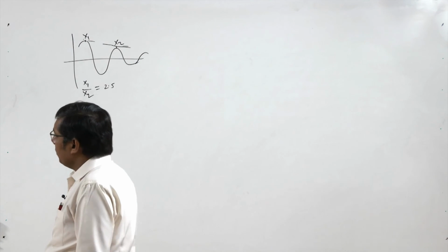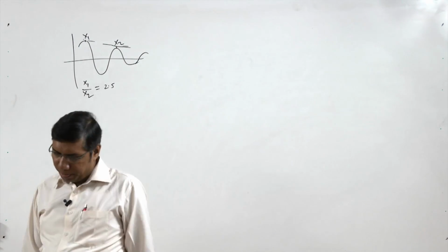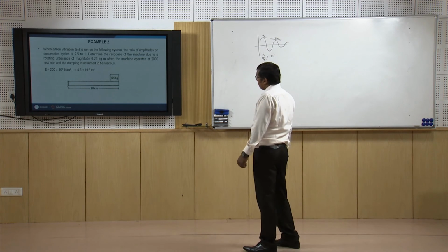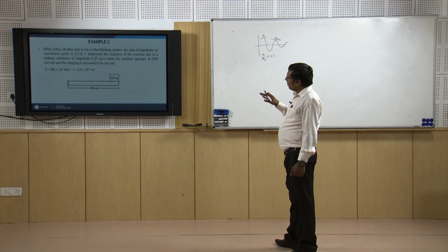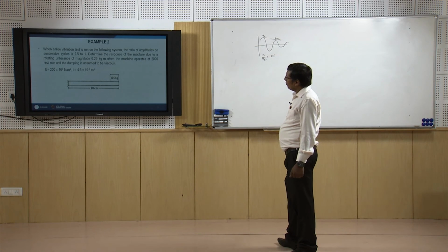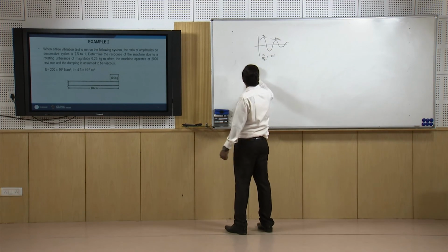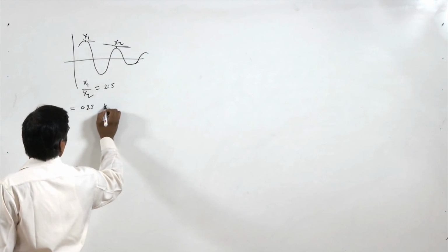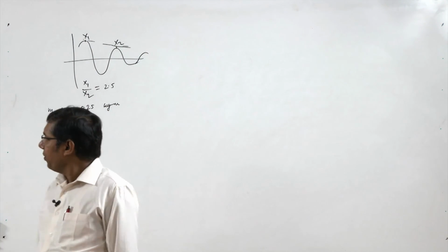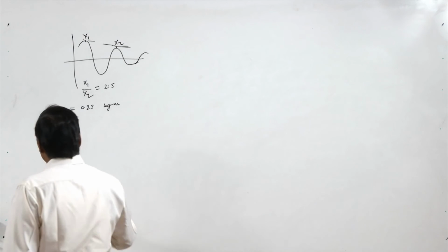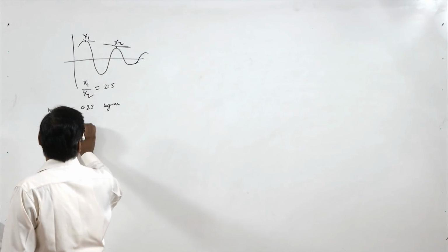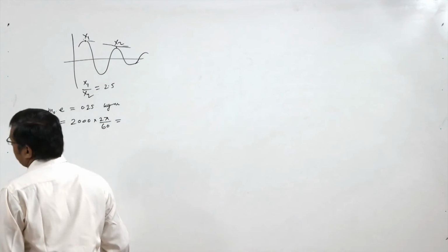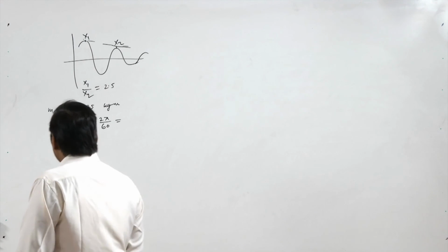Now there is a rotating unbalance in the machine. There is a machine of 125 kg on a cantilever beam, and the machine has some rotating unbalance m0 e, that is 0.25 kg meter, when the machine operates at 2000 rpm. So omega equals 2000 rpm, so it is 2000 times 2 pi by 60 radian per second, and damping is viscous.